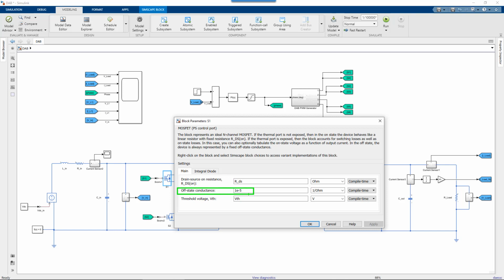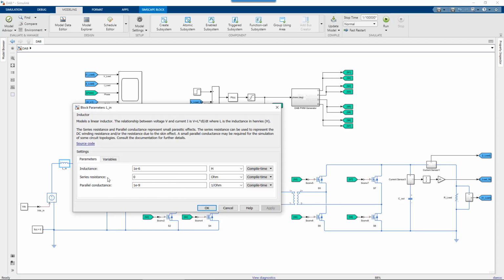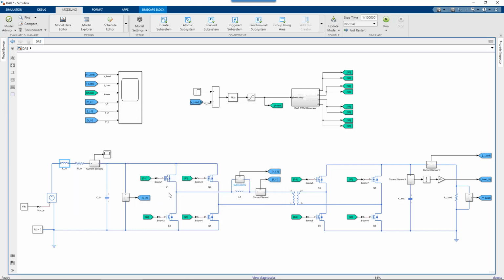Make sure those are all in the same range. So don't have some with like 1e to the -5 and then come over here, well, there it's 1e to the -9. It's not making a difference. But in general, keeping everything in the same order of magnitude or a couple orders of magnitude can be good. That's the sort of thing that might inject these weird high frequency time constants that you don't need that are a problem for a solver.